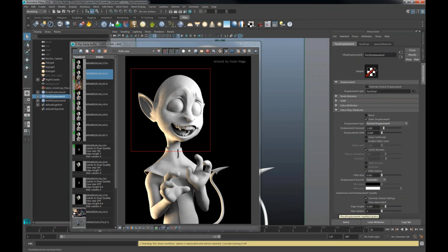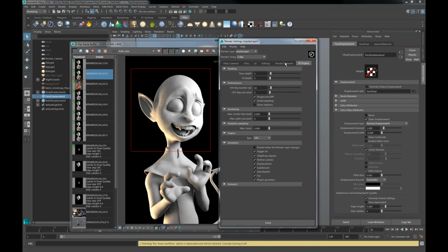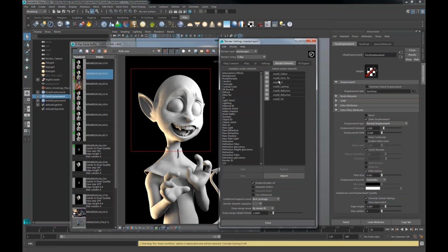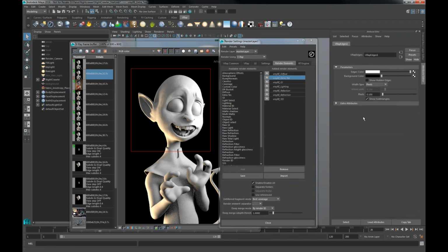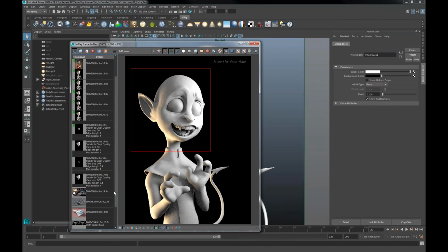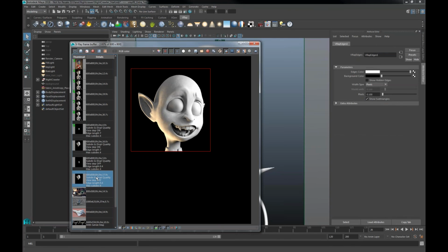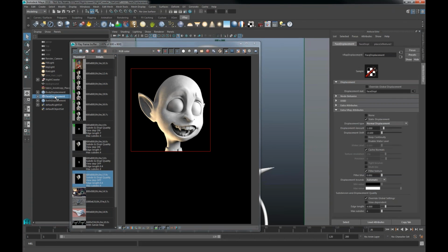And if you want to see how V-Ray is subdividing your mesh, there is another trick to see that, and this is by using V-Ray extra texture render element, and in it I have plugged edges texture. And make sure you have here this show subtriangles enabled. And since we don't have so much time, I have pre-rendered this, and in order to explain you what are the settings. And this was, so let's go again in the displacement.